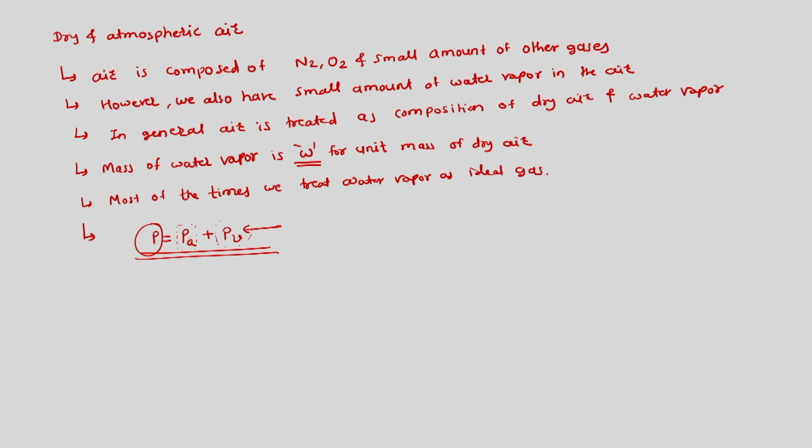So we need to find out, suppose, enthalpy H, which is a function of T. That can be found as H_v of T, which for us is equal to Hg of T. So we practically mean that we will go to the vapor pressure, treat that vapor pressure as the saturation pressure, and at that saturation pressure we will see in the steam table what the saturated vapor enthalpy is.